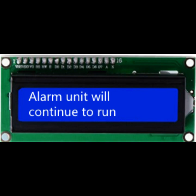Alarm unit will run or shut down. The unit that goes into alarm can be set to either keep running or shut down. The default is to leave the unit in alarm running, but ductwork limitations may dictate that it is better to shut down the unit in alarm.